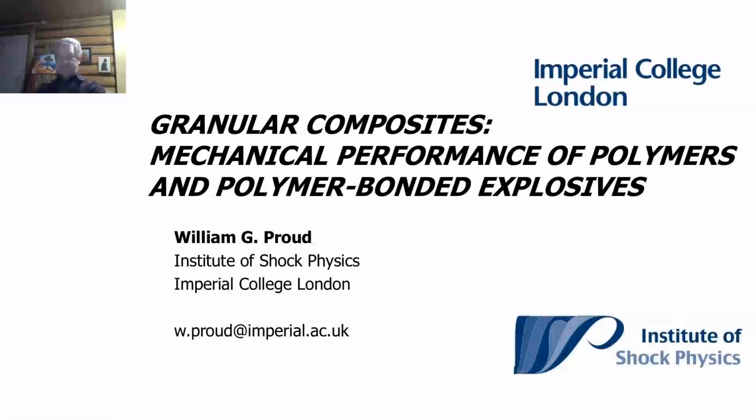That is correct. The strain field generated in, say, a Brazilian test does vary through the sample, but it can be calculated. It has been calculated for our samples. Because I haven't got the data immediately at hand, in the next talk I give, I will start by showing a digital image correlation of a Brazilian sample and the calculated field, because I have that in my file somewhere, and I can show you that there's a great degree of similarity between the two.